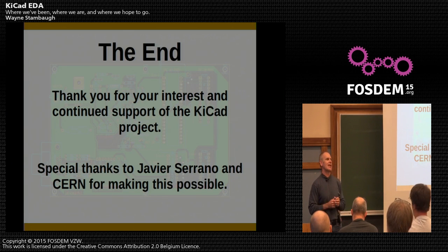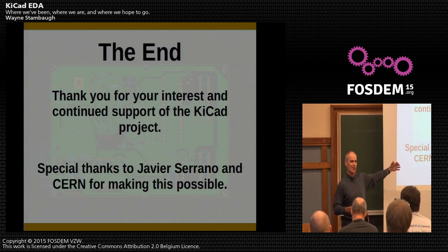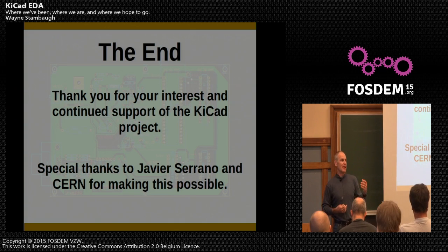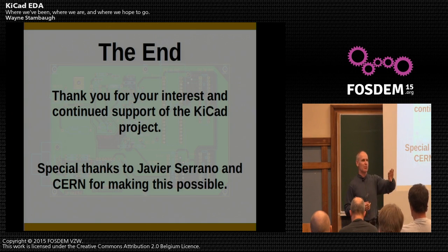Basically, the way I'm thinking of the file format and working the attributes internally in the data is that the goal is to be able to add an attribute to any object in the PCB. Now, whether that makes sense or not, I don't know. But those attributes the schematic editor or the board editor may not do anything with them, but it'll save them and then put them back out, so that if you want to post-process the net list, they'll always be saved in the net list with the object that they belong to.